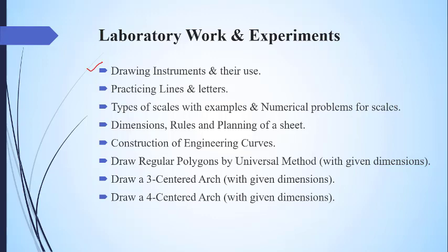The other topic for laboratory work will be practicing lines, that is, what the lines are and how they can be drawn, and what the different lines are and where they can be used for different purposes, for example, thick chain line, thin chain lines, dimension line, etc. These types of lines would be covered in practicing lines. And we will also see the letters, how a letter can be written, or how it can be shown in an engineering drawing sheet.